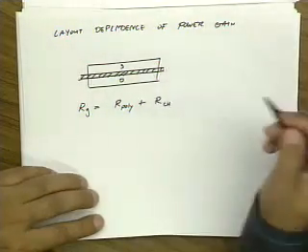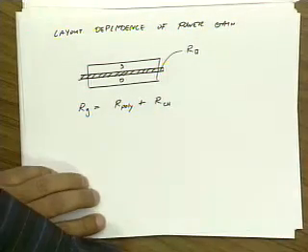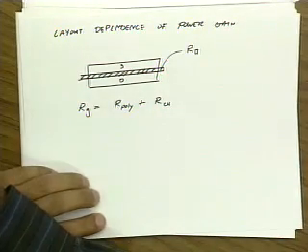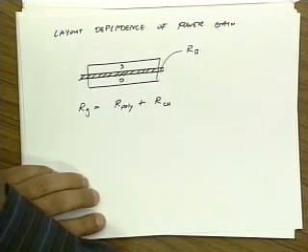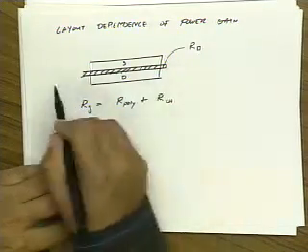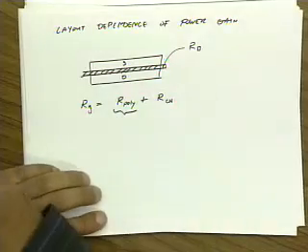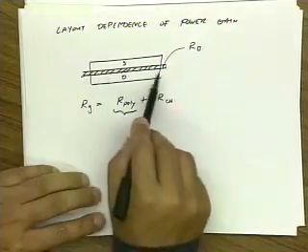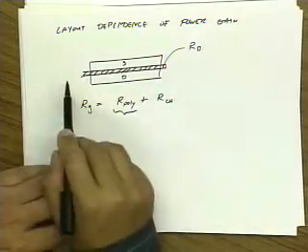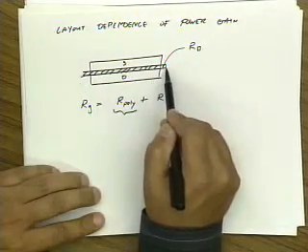So usually when you design a transistor, someone will tell you, yeah, this poly is silicided and it has such and such sheet resistance, right? And of course you want to get the one that has the lowest sheet resistance. So you just calculate the physical resistance of this, and that contributes to this term. Now it turns out that this is actually a distributed structure because the current that goes into the gate doesn't all flow to here, right?